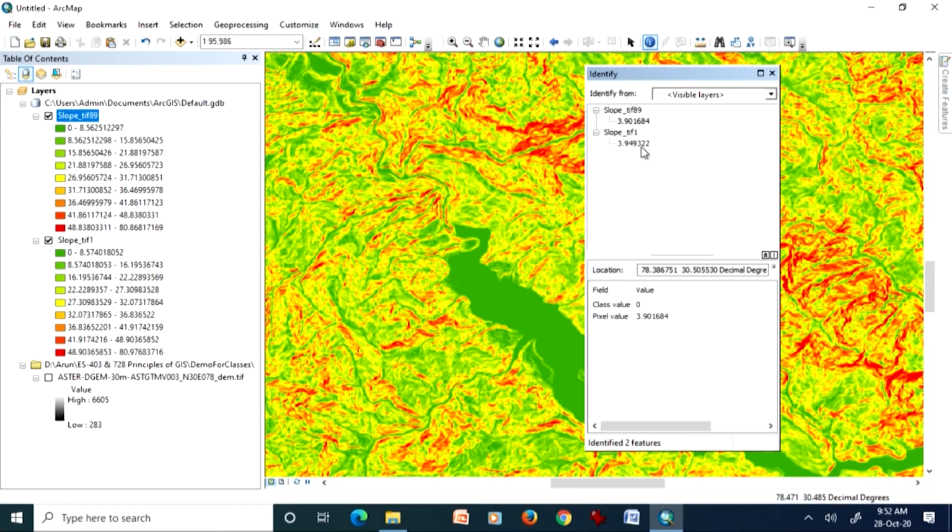So it is always good, always desirable, that we take care about these X, Y and Z scales, that these should be equal. If they are not equal, then we should use the Z factor and convert. It is rather easy to convert our meters into DD, which I have done in this demonstration.